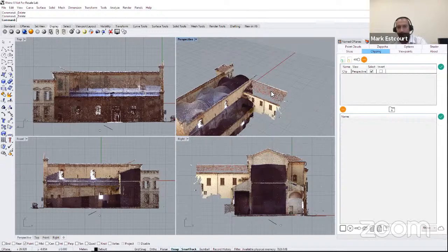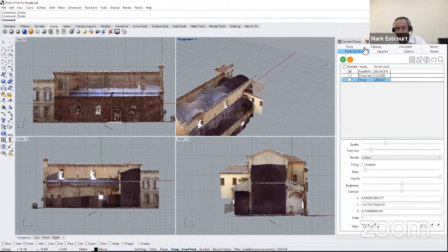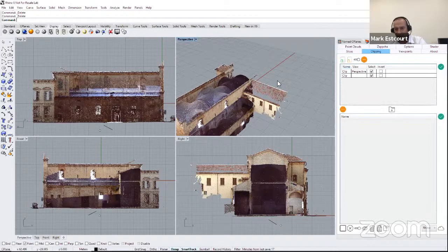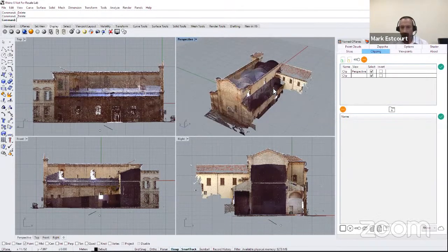You could delete that data if you wanted to using our clip-in feature. And like I say, you can recover all this information. It's non-destructive, so you can delete that. Okay, so that's gone. Okay, so restore the point cloud back to its normal form. So select the right one, that's it, and it's come back. So even though you have deleted it from your view, it hasn't actually deleted the original file, and that could be quite annoying if you had done that.